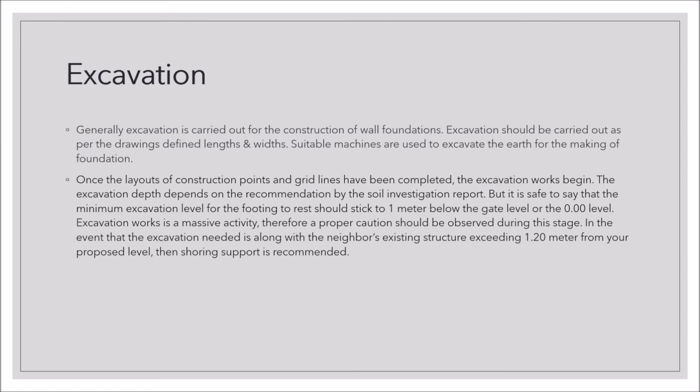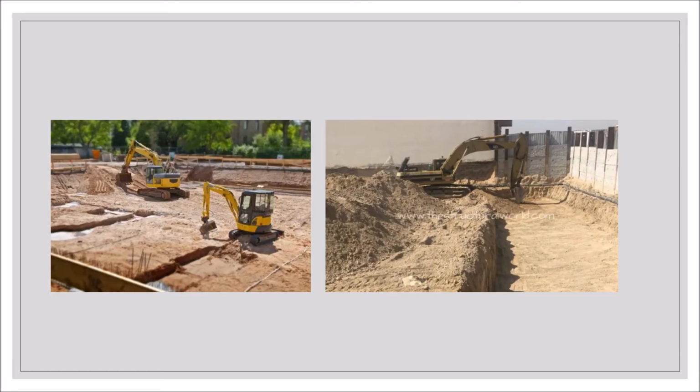Excavation work is a massive activity, therefore proper caution should be observed during this stage. In the event that the excavation is along the neighbor's existing structure and exceeds 1.2 meters from your proposed level, then shoring support is recommended. Excavation is needed primarily for the foundation or for basement work and so on. So it is needed to dig the soil.